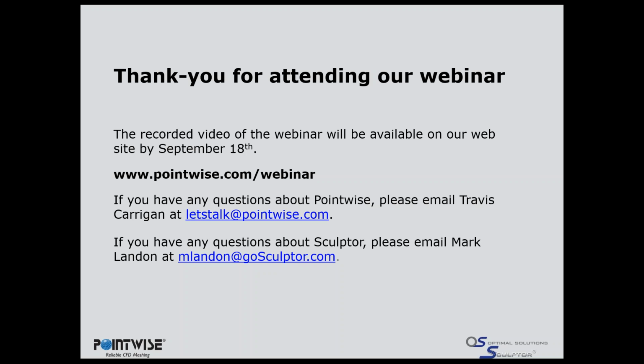Okay. Once a surface mesh is modified with Sculptor, do the viscous layers and volume mesh get recreated automatically, or do they need to be recreated manually? I think both of us could tackle this. This doesn't require remeshing, right, Mark? I mean, we're morphing this mesh and just modifying the point locations and then dumping that data out. There's no recreation or regeneration of that mesh. You want to say a couple things about that?